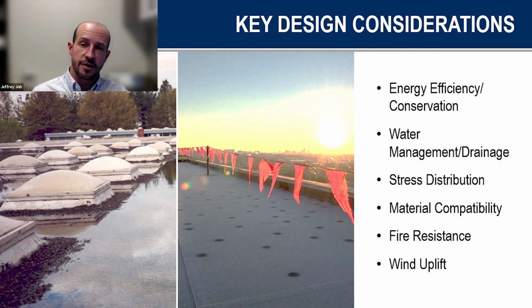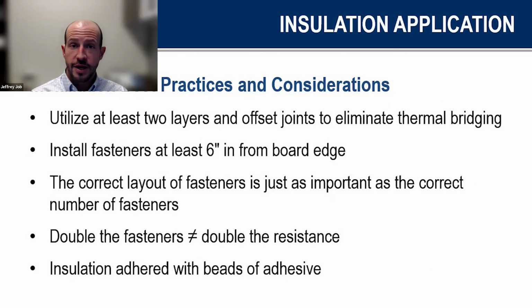Of course, we've mentioned the fire performance. You can get Class A fire ratings with this coverboard directly over a combustible wood deck. So you can put that down, put a membrane over the top of it, and that's going to meet the Class A requirements per UL in a lot of cases. So that could be done there.